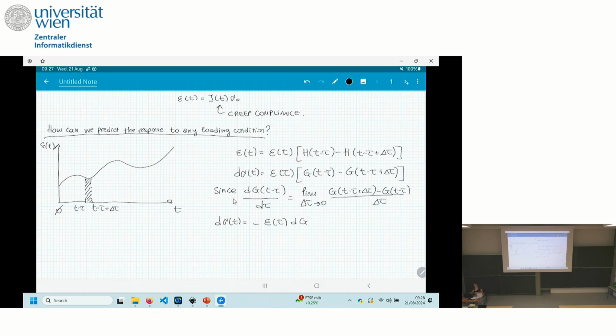Any requirement about choosing tau? I know you can choose it as small as you want, but from a practical point of view? I mean, you do have some problems when you have singularities in the responses. In fact, the dashpot is one of the problematic ones, because the smaller you go, you still have the singularity.